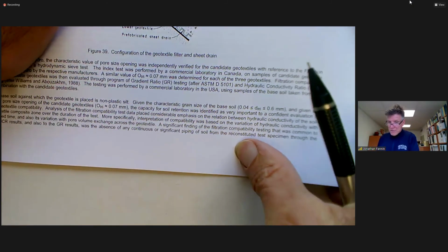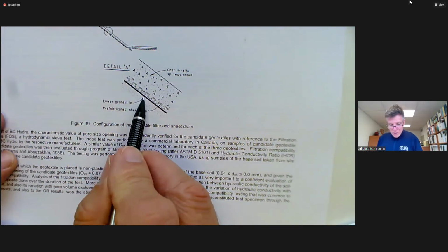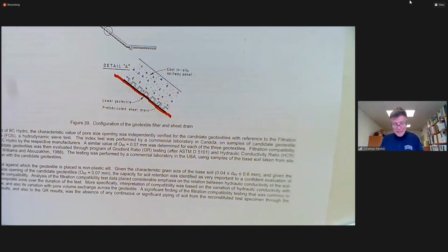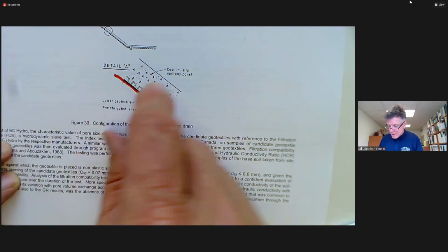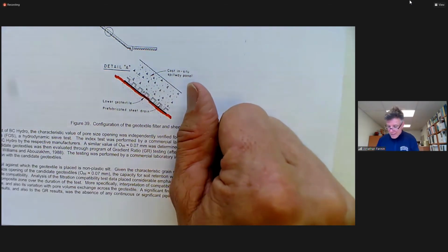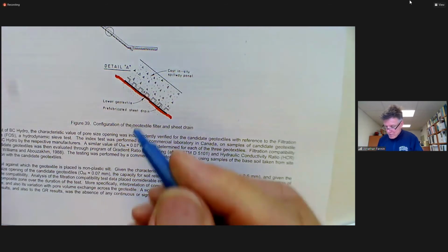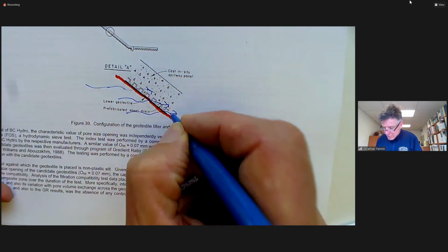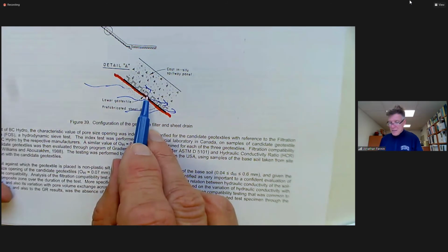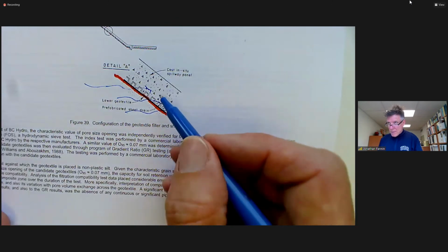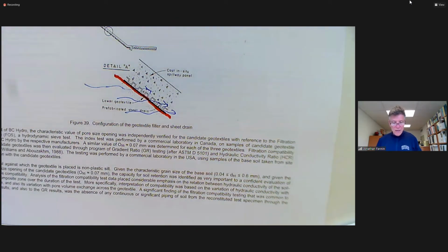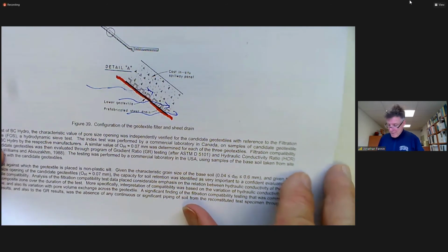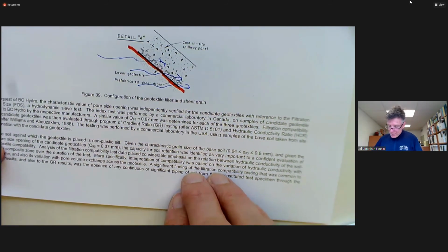And the arrangement that was conceived was to have the geotextile here in red, a prefabricated plastic geosynthetic cuspated drainage panel, and then cast the concrete panels on top of that. So the interest was in unidirectional flow of seeps in the base soil, and the filter's primarily keeping the drain free, so that where we have any cracks or joints in the spillway panels, that water can be drained in a cuspated drain that is not compromised by piping of base soil into it. Okay, that's basically what we had to do.